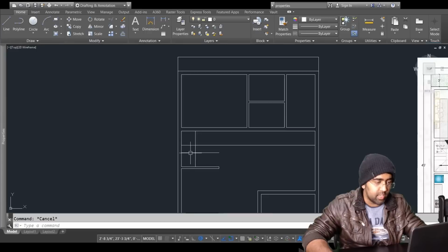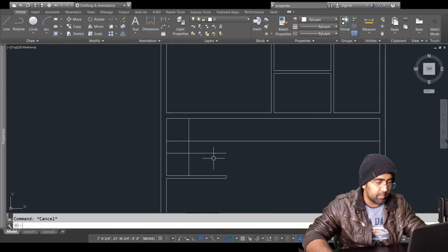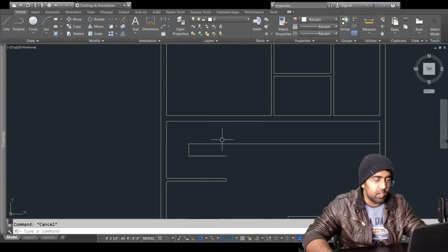Okay, so now instead of trimming everything, I can use the fillet command. So F, select this line, and then select this line. Done. Alright, and then we're going to create a line here, so I can just hover my cursor here, take it up, and then it's not intersecting. So now click on this snapping option, and then select maybe intersection, okay.